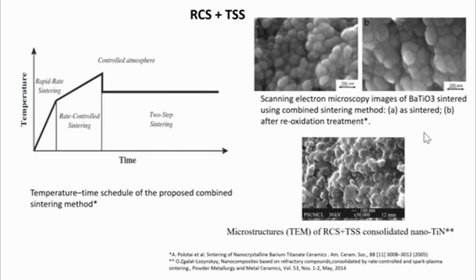To produce materials with a volume of more than a few cubic centimeters, a general process of sintering composites in hydrogen and nitrogen was developed based on dilatometric experiments on sintering of pure titanium nitride and titanium nitride in composites with nano aluminum nitride and silicon nitride.